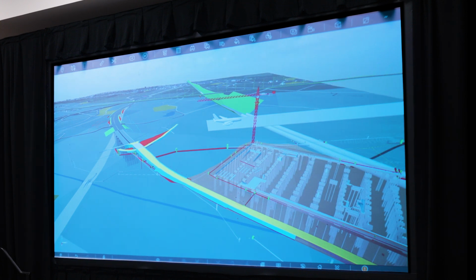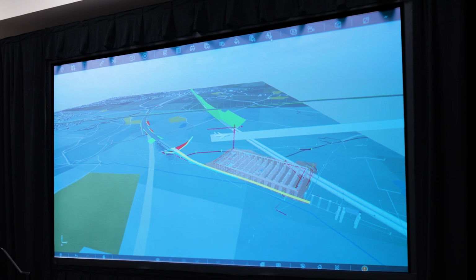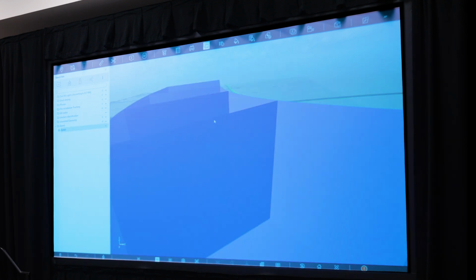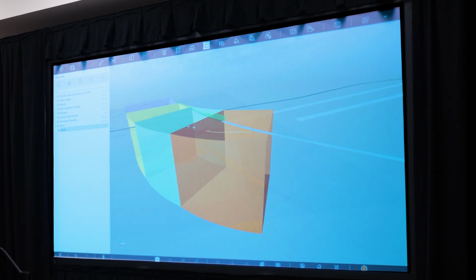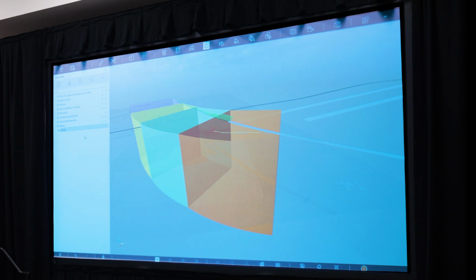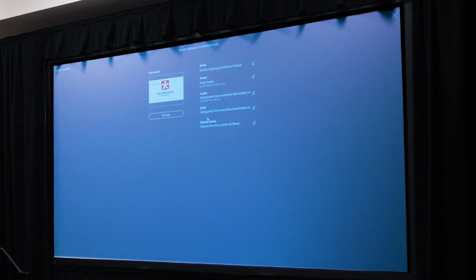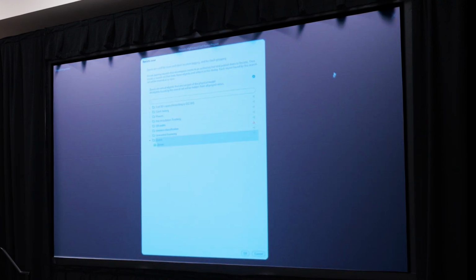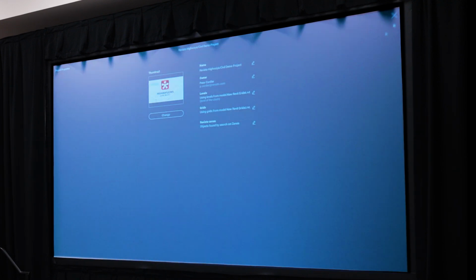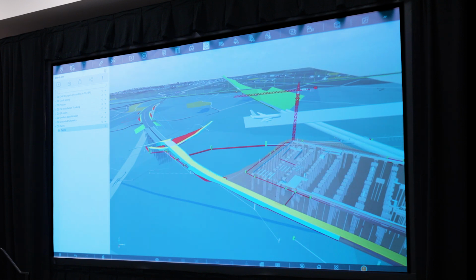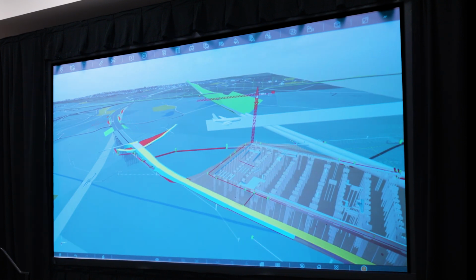I'm going to show you the zones and what they look like. So if I get my search sets up, I've selected my zones. You can't see them. The only way to see them is if I isolate transparency. So when you bring the zones in, you create a search set which ties the zones together. You then go up here, project properties, select the search set that you want to use for the zones. And then when you do that, if I just go to the home view, they basically disappear. But they are still there.